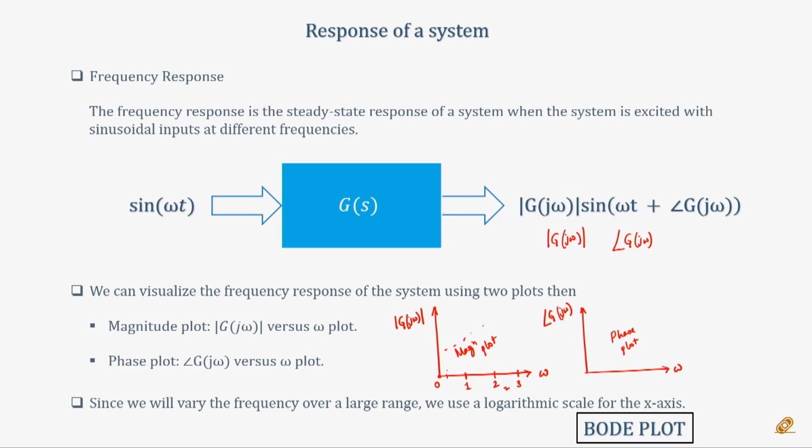One of the most important applications of the Bode plot is that if you get the Bode plot of a system, even if you do not know what the system is, what I have just said can be done without knowing the system. Suppose you have a black box. You can keep giving sinusoidal input to the system while changing the frequency, and at the output you measure the magnitude and the phase change. Once you get that, you have information about the system for different values of omega. We can use that information to find the transfer function of the system,